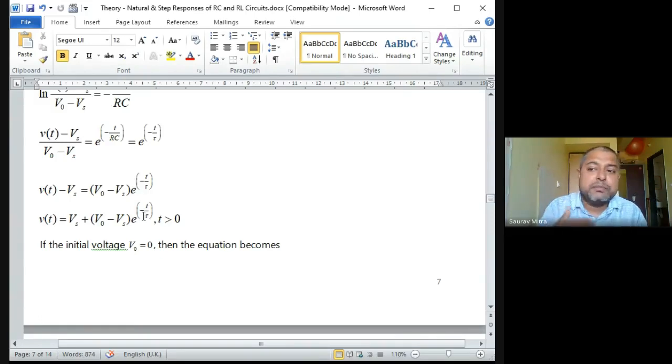You have to first define how much is the R and how much is the C, and then plot the same graph for different values of R and C, different combinations of R and C. Three combinations are important: one is fastest, one is medium, one is slowest. Keeping C constant, if you are increasing the value of R, you will find that the graph is getting slower. If you keep the RC value less, you will find that the capacitance is charging very fast. What is V0?